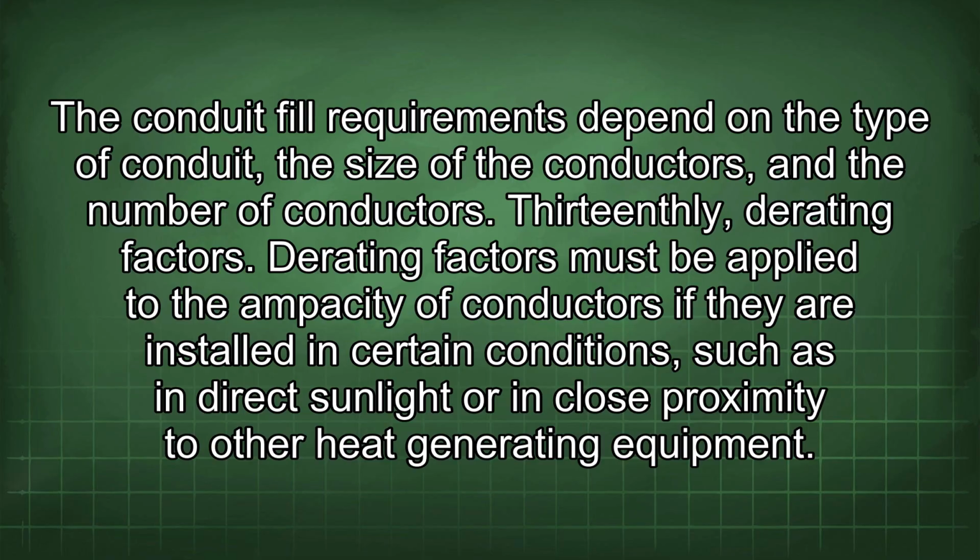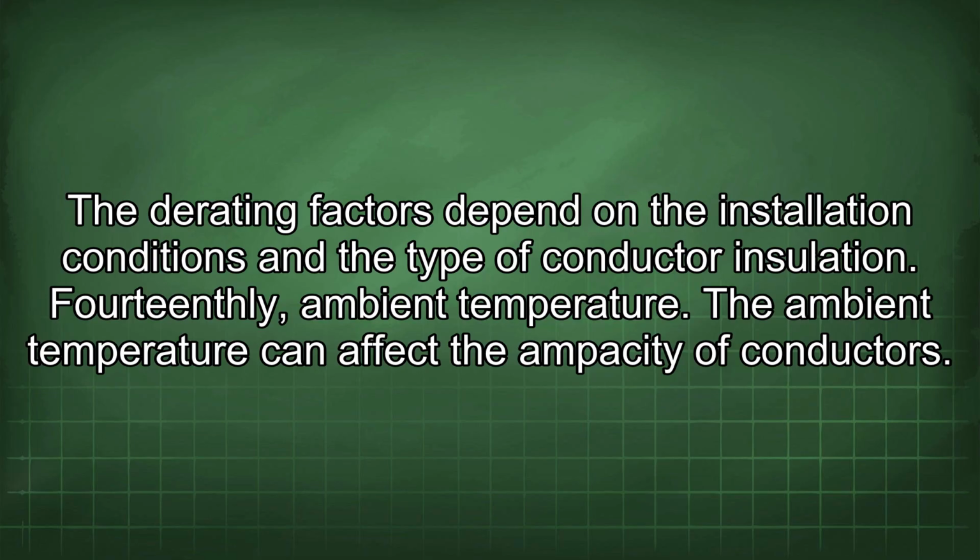Derating factors must be applied to the ampacity of conductors if they are installed in certain conditions, such as in direct sunlight or in close proximity to other heat-generating equipment. The derating factors depend on the installation conditions and the type of conductor insulation.